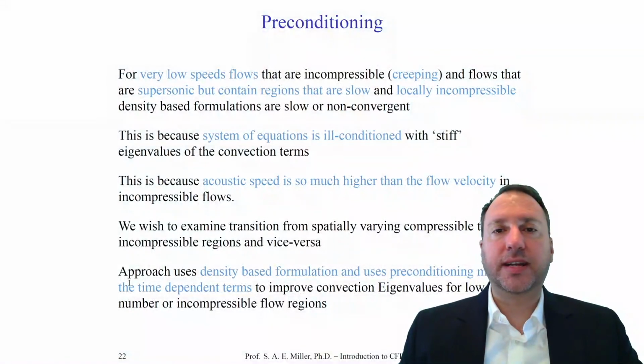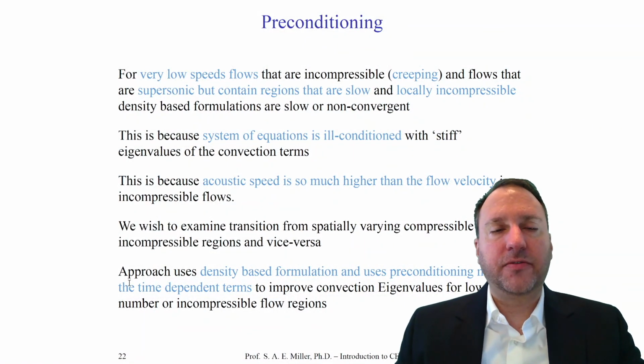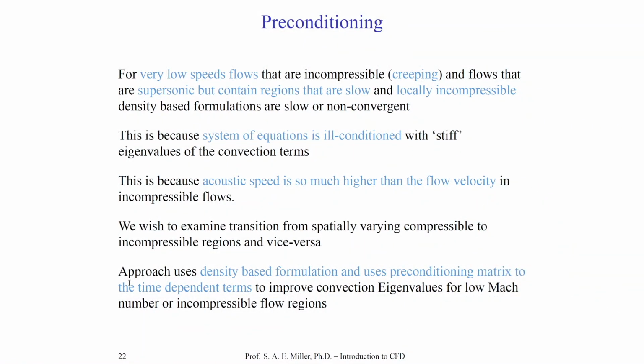Now we'll look at preconditioning techniques. For very low speed flows, which are incompressible or creeping, or very high speed flows that are supersonic that contain regions that are very slow and locally incompressible, the density-based formulations, which we showed, which are traditional, are very slow to converge. This is where the idea of preconditioning techniques came in.